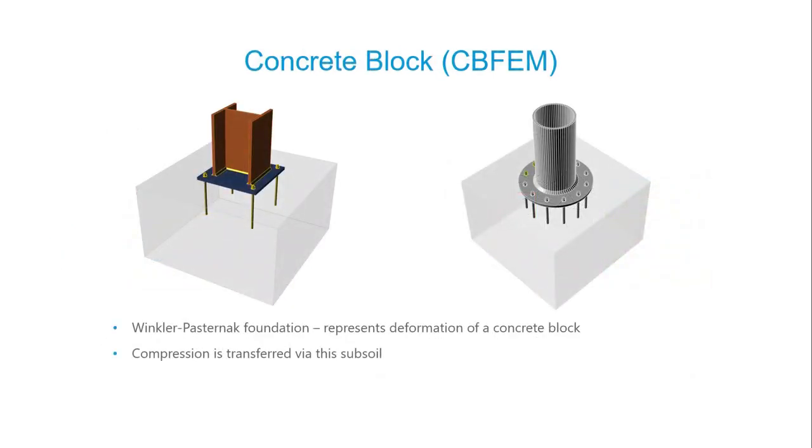Then we have the concrete block. The connection between the base plate and the concrete block is able to transfer compression only. The compression is then transferred via Winkler-Pasternak subsoil, which represents the deformation of this subsoil.